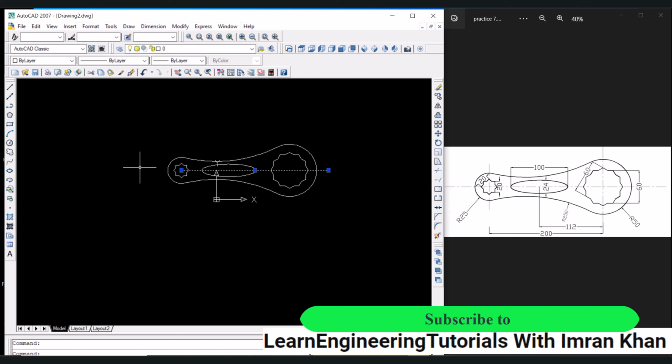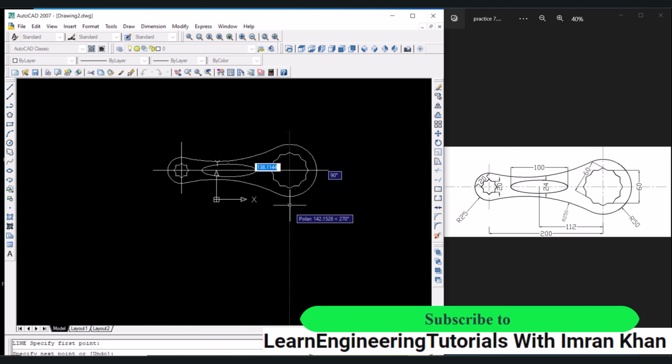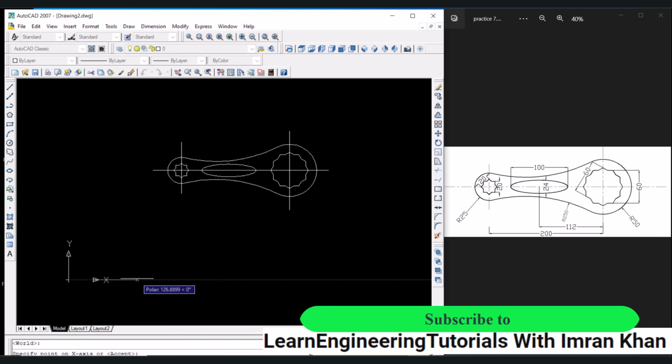extend this a little bit, add both ends, click on line, drag this quadrant, click below, press enter again, drag this quadrant, click and click below, press enter. Move this UCS icon, so UCS, enter, click anywhere below, click on the X direction, click on the XY region.